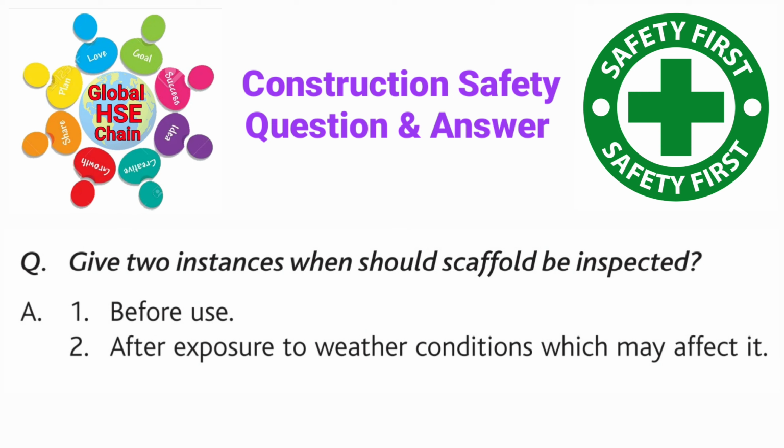Question is, give two instances when should scaffold be inspected. Number 1, before use. Number 2, after exposure to weather conditions which may affect it.